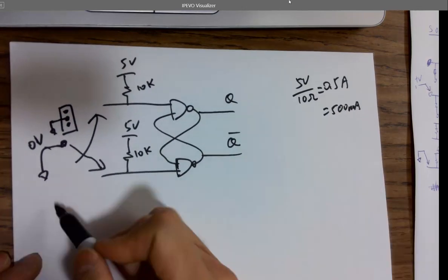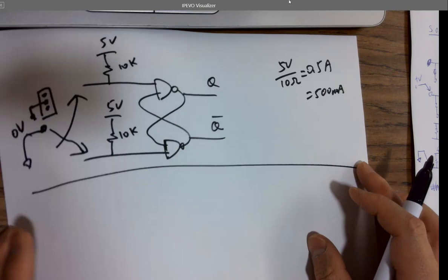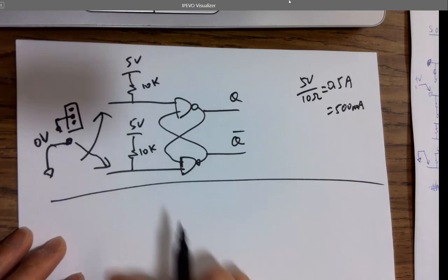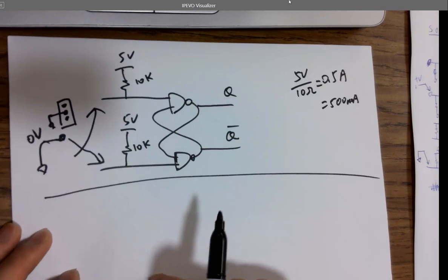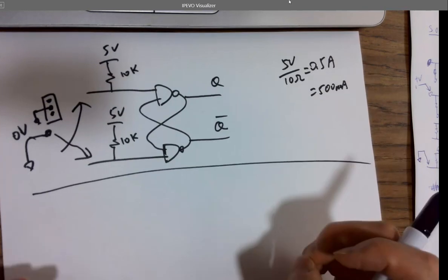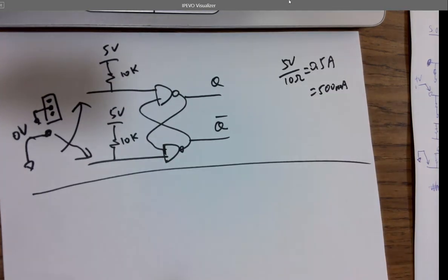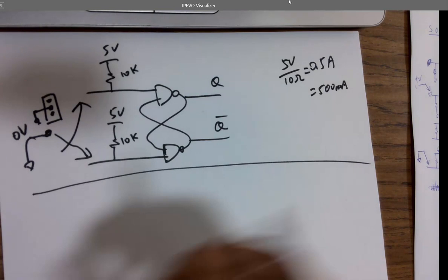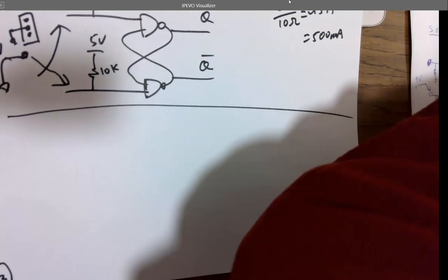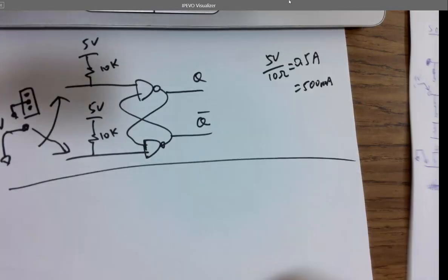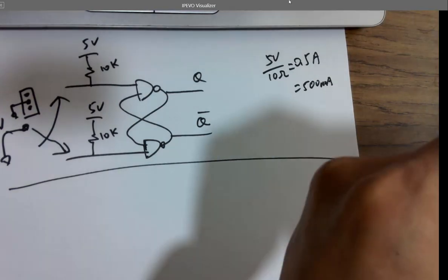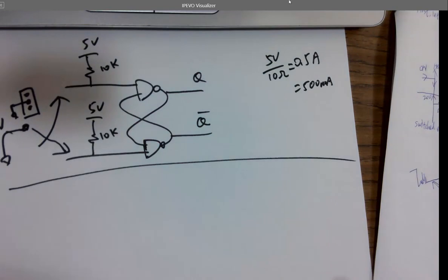What about the push button? A lot of times you hate switches because you can easily break the little knob on top. So what about the push button? It's easier, just push, right? It hurts your finger if you have a little print on your finger. Get nicer buttons. How do you debounce a push button though? Could you use the same circuit to debounce the push button? You just force both of them to the end of the... wait, no, that wouldn't work.